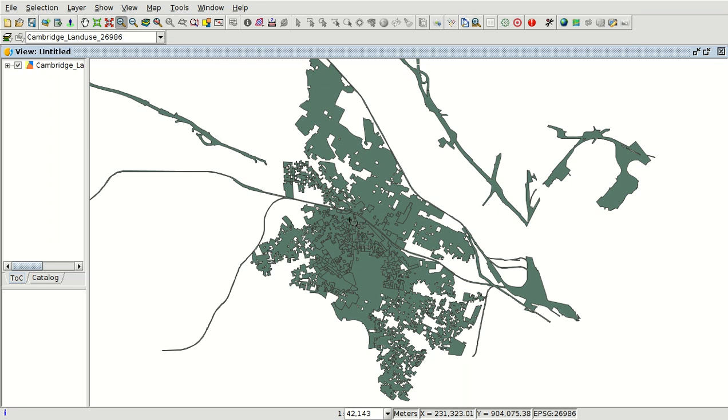You can check that it's correct with the other layers, for example this one, or you can use a web map service to check if the vector layer has been reprojected on the fly correctly. After reprojecting this layer on the fly, you can export to a new shapefile, and this shapefile will be in the new reference system.